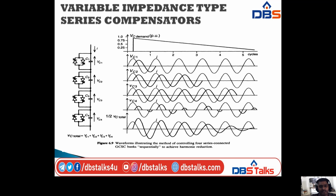So here I am taking four GCSC schemes, and on the right side we have the waveforms of these four GCSC schemes. The first waveform is for the fixed capacitor voltage, next we have Vc1, Vc2, Vc3 and Vc4, and lastly we have the total capacitor voltage.